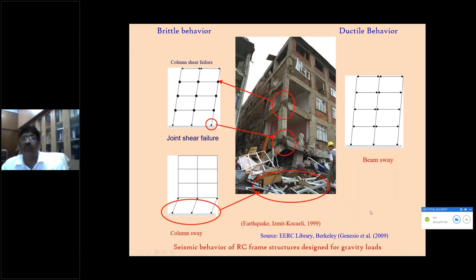Therefore, while designing for earthquake loading, we have to design the building so that it as a whole has sufficient ductility, the ability to withstand the forces, so that local failures can be allowed in the beams only, nowhere in the columns or joints. That is very important for you. So while analyzing and assigning the sectional properties of the joining members, the designer has to be very careful, and the reinforcement you provide also matters. This gives you the design approach for the structural system against the lateral forces from earthquakes. The same is the case for blast and other loading effects.